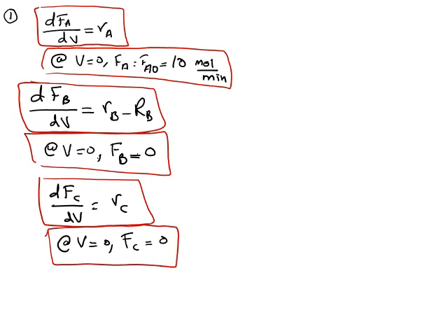Okay, remember, Shabab, the logic between these steps? It was based on the fact that we need to solve the design equation. However, when we write the design equation, we introduce a variable. In this case, it's the rate fraction, so we provide an equation for it, and so on. And here in this case, we are providing a variable which is RB, the capital RB. So we need to provide an equation for this, and luckily we have a very simple equation which states that RB equals KC times CB. And we're gonna need this equation as well to plug it in. Alternatively, we can write this equation at the end.